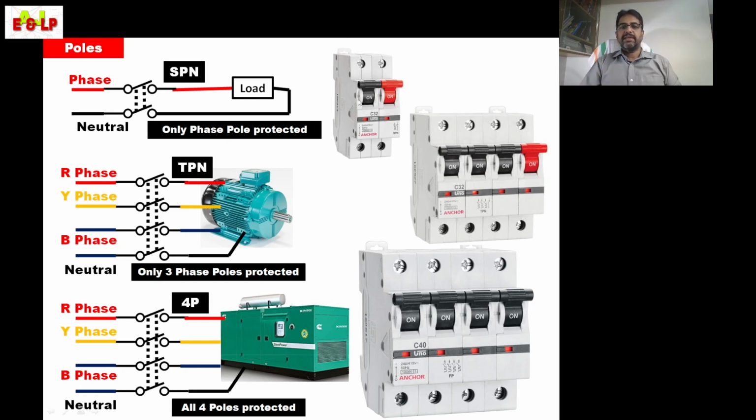See here the MCB for the isolator, the neutral part is shown in red. Next is TPN, triple pole neutral, means it has four poles, but the neutral pole does not have protection, but it will work together being linked.